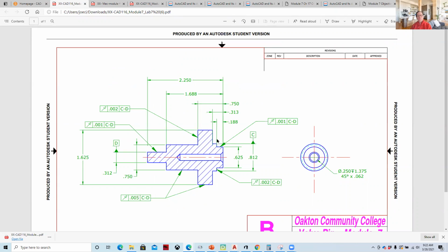And here's another mechanical, and we're upping the level of knowledge by including GD and T symbols, or geometric dimensioning and tolerancing, because when you really start to work with manufacturing today, the machines are extremely accurate to 4 decimal places, even 5. But as you learn how to design for manufacturing, all of those things cost.